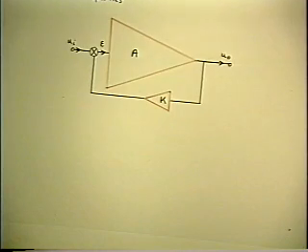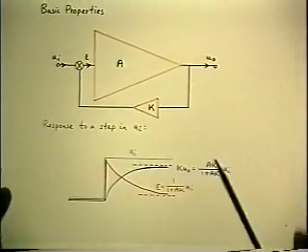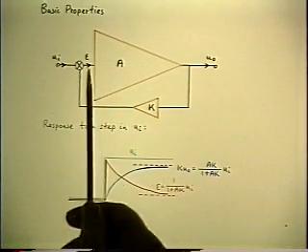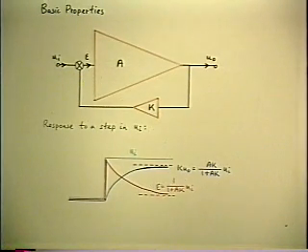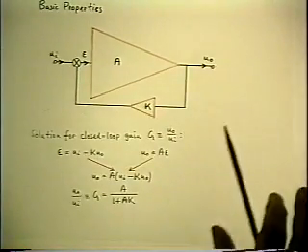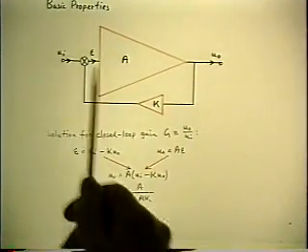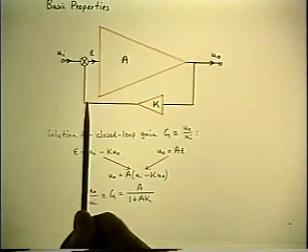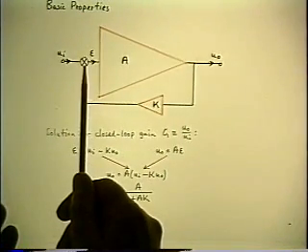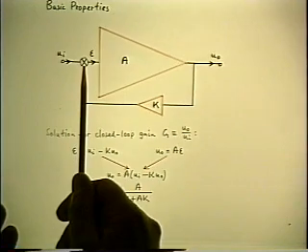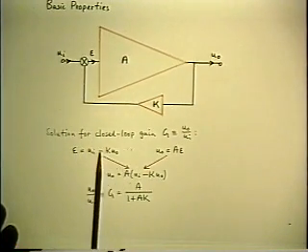Back here in the original picture, I defined these quantities, the error signal in particular, as epsilon is the input signal minus the feedback signal. In other words, I've actually defined this junction as a differencing junction, not a summing junction, by making the minus explicit.